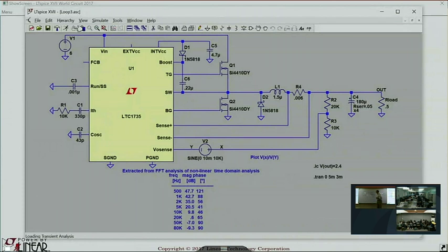And the reason why it's not exactly correct is slope compensation. Slope compensation changes the story a little bit. See, the thing is, if I reset this flip-flop not according to inductor current, but current plus something else, the dimensions of current plus something else is not current.